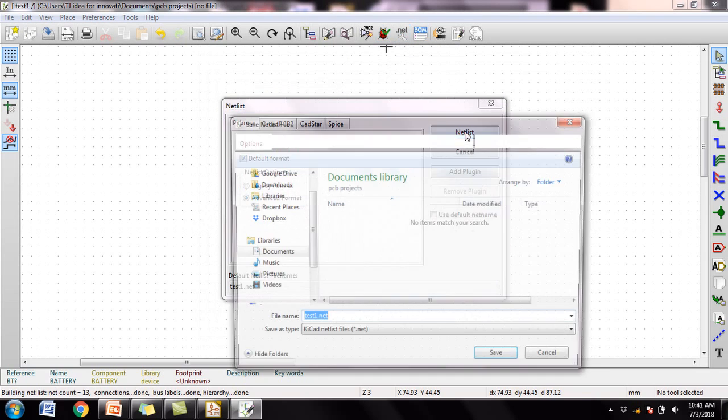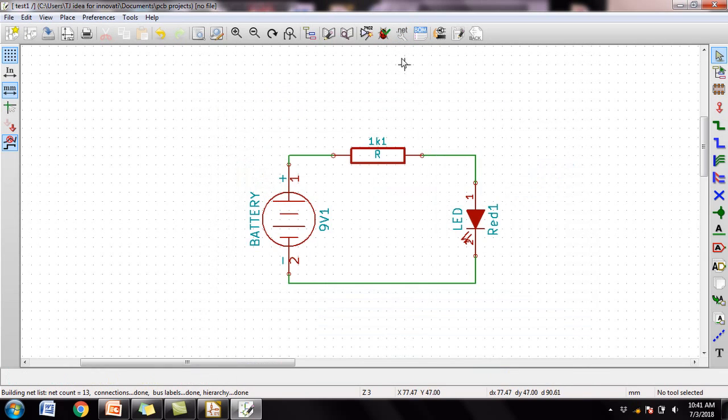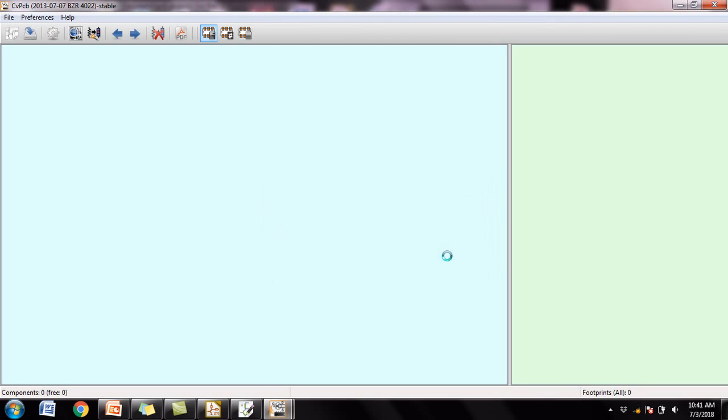So the netlist, once you have created it, will list all these components to the CVPCB listing, which is where the schematic to modules mapping will be added. For that you can check it out now, click on it. So this netlist will be created, and for each of these components we should add a certain module.